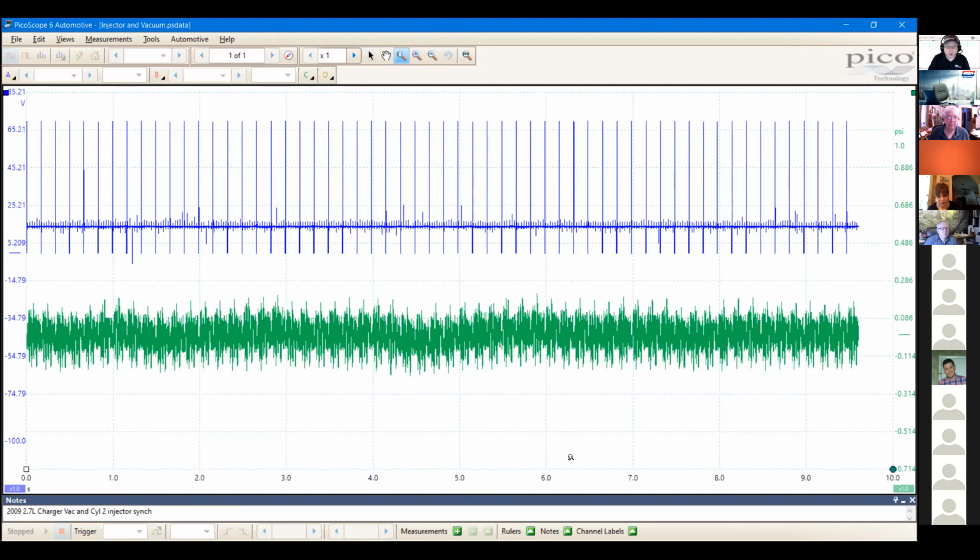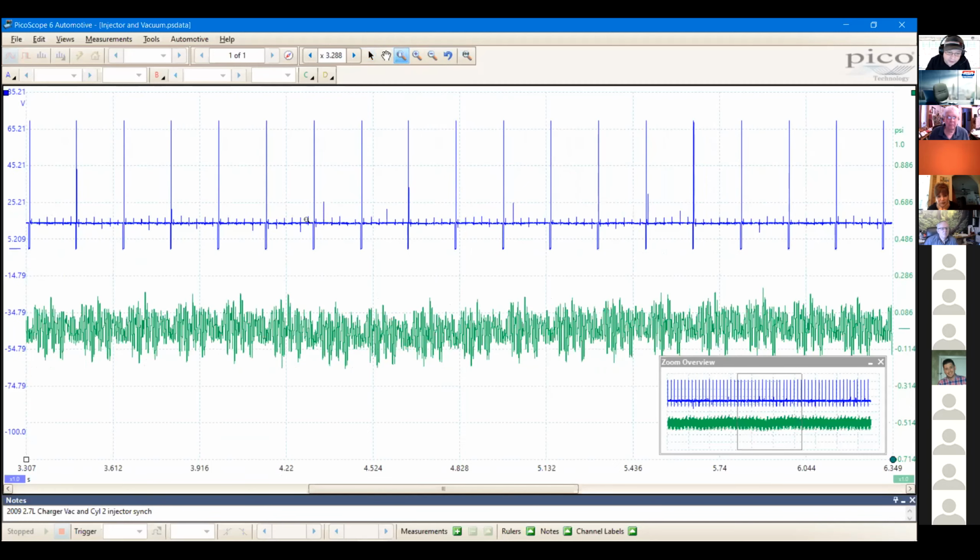Or I could just wing on in here and say, look, between this firing event and this firing event, I have all of them. So from here to here is one complete cycle, 2 crankshaft revolutions. Here is where a problem lies with many, many technicians.